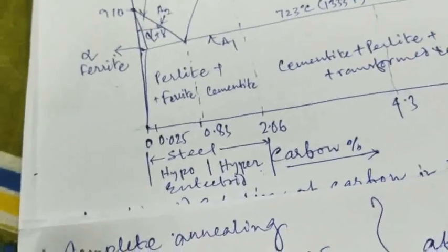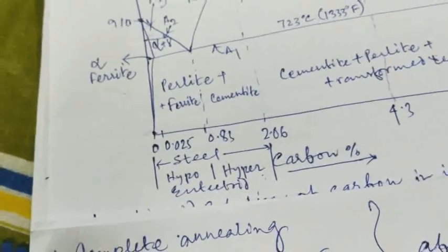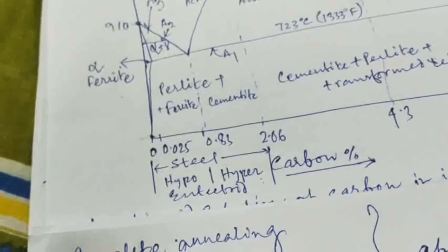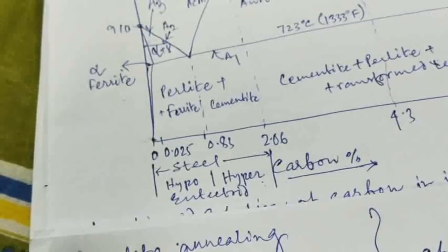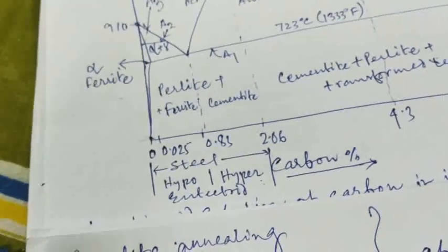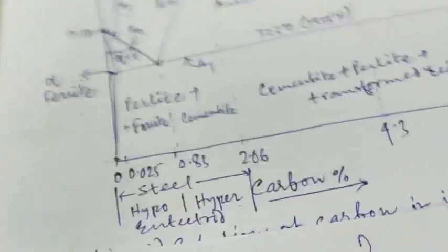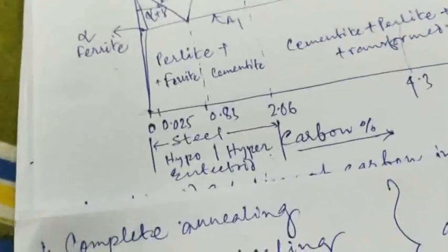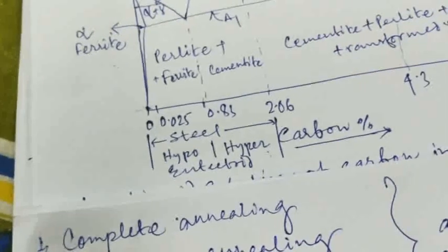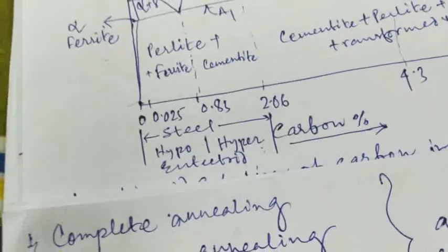Spheroidizing annealing gets globular pearlite. In globular pearlite, the cementite appears as spherical particles dispersed on the ferrite matrix. Spherical pearlite is not only low in hardness but also convenient for machining. In addition, the austenite grain is not easy to coarsen when heated, and the deformation and cracking tendency is small.